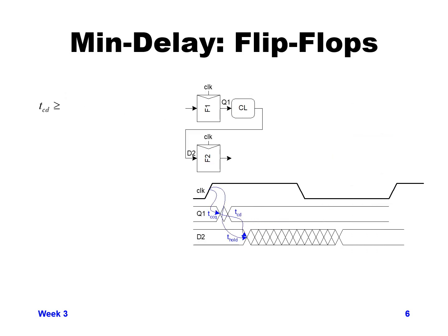So in the previous several foils, we've been going through the delays related to what we call max delay, or the maximum frequency that you can operate at, or in other words, the minimum cycle time that we can get through our combinational delays, between how fast you can get the data to flow through your logic from one clock edge rising to the following cycle's clock edge rising. Now, in the next several foils, we'll be talking about min delay.